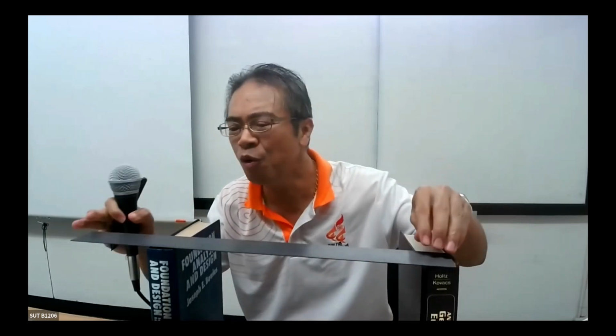If this is a simple beam, the deformation is this one. Very simple. Again, if I change this into a beam with an overhang, and I put the force here, you see, before this the beam just curves, and here is a straight member. There is no moment on this part, so it's a straight member. And if you put the force like this, this is going to be the deflection. If you like to draw the deflection, you have some homework to observe this kind of thing. Do it at your home.